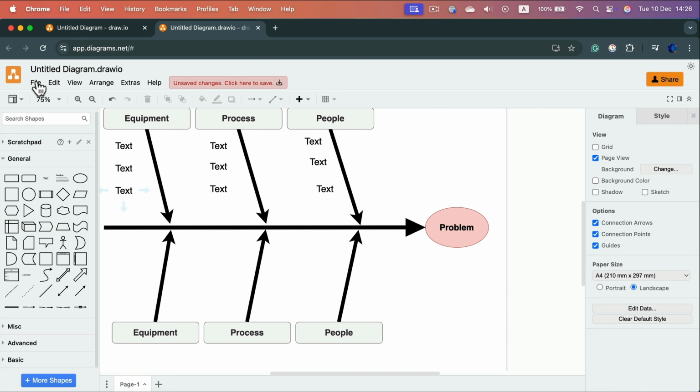How can we add a new column to existing table in diagrams.net? First, let's make a table using the basic table tool here at the top. Alright, how can I add a new column on the right? Be sure that the table is selected. It's important. Select the table and then click on the table tool once more. Instead of the table tool, you will see options to add column on the left, add column on the right, remove column, add rows, remove rows. So now we can just select this one, add column on the right, and here it is.